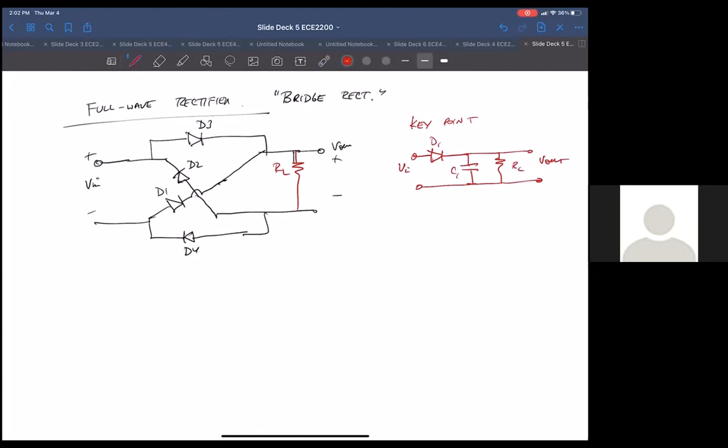All the other circuits were kind of like this in some ways. Here's our Vin, this is our V out. But Vin, because it's a voltage, needs to refer to something, right? It's a voltage with respect to something else. Vin is referred to ground, and in fact, V out shares the same ground with Vin. So they're both referring to the same node on the circuit.